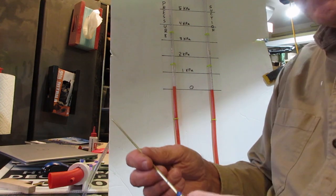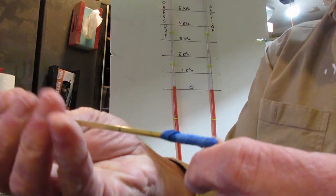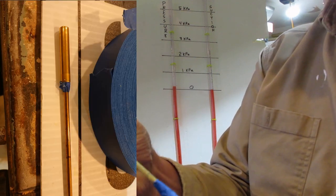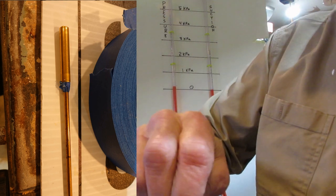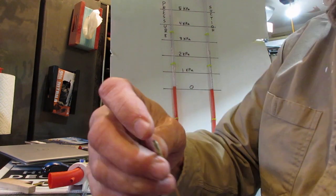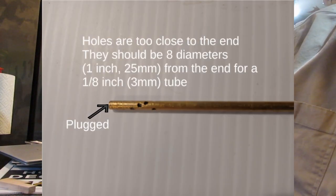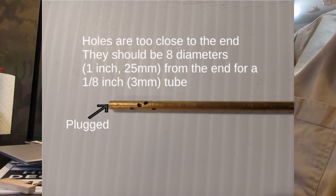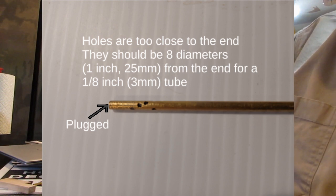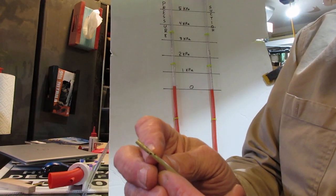To adapt it to my vinyl hose, I just literally wrapped it up with some tape until it was a tight fit. Nothing very sophisticated. Again, the end is plugged with a little bit of epoxy, and you want about 8 tubing diameters. So if this is a 1/16, that would be 8/16, half an inch, or 12.7 millimeters, from the end to where these holes are drilled.